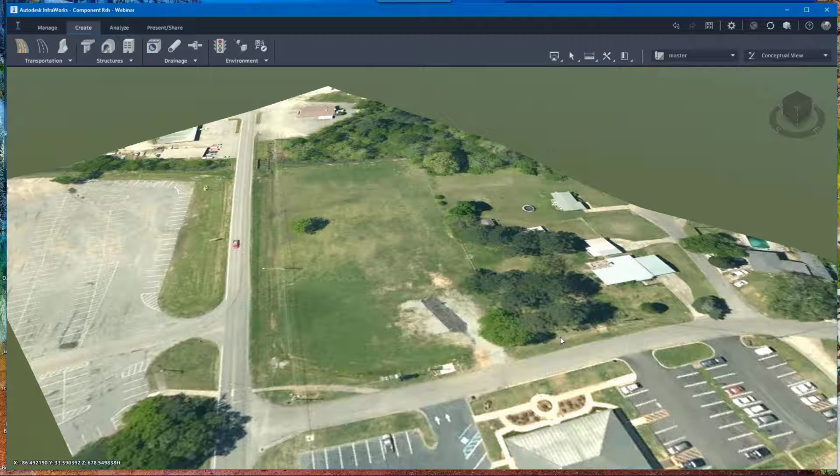Okay, so I'm going to start out by creating the concept components first, and then I'm going to incorporate them into the component road. My personal preference is to not create them on the fly and start off with the entire section of road. I usually like to do something about 50 to 100 feet long.